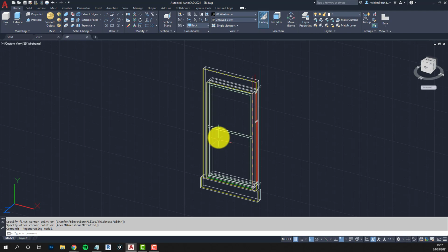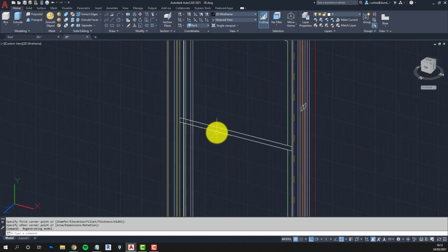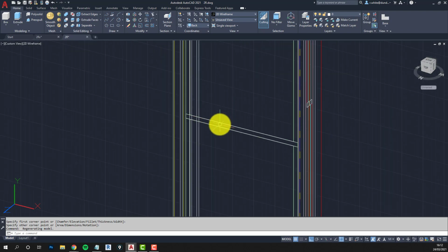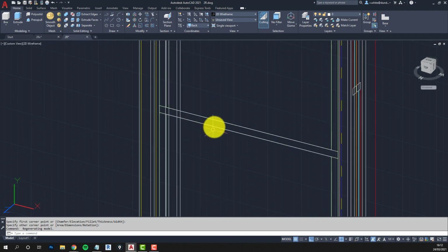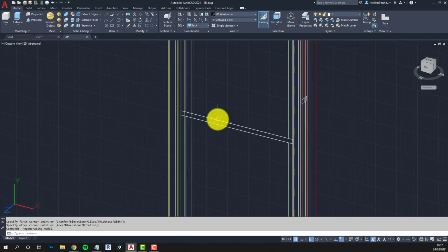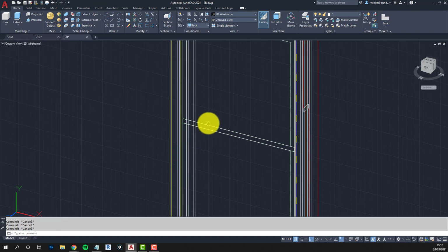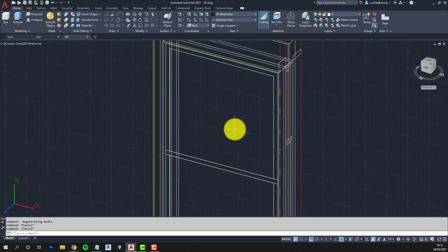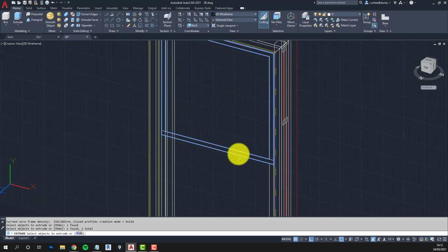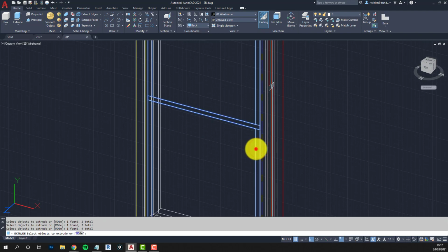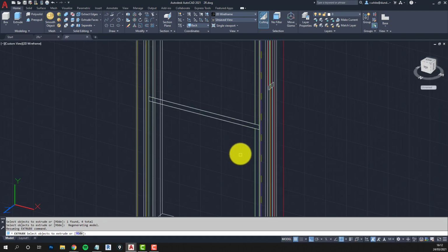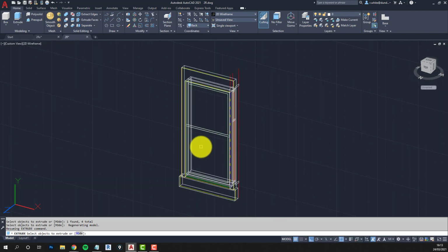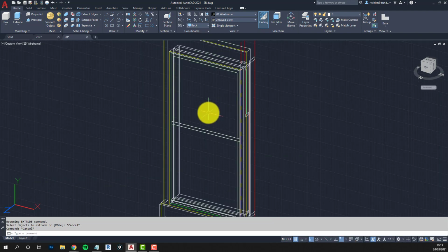Okay, let's have a look at that in 3D, see what we've got. Okay, now all of these are going to be 50 millimeters deep. So let's just do the extrusions. So we've got 4 extrusions to do. So EXT, and it should pick the newest objects. Generally that's how AutoCAD works. We should be in control. Oops. Notice the newer versions, if you deviate, you can lose your selections very easily with these newer versions of AutoCAD.